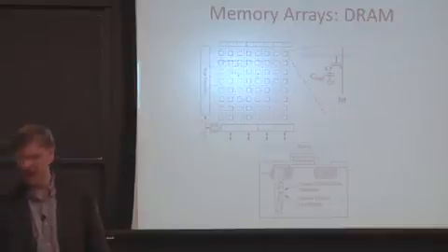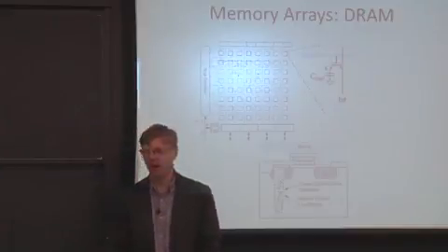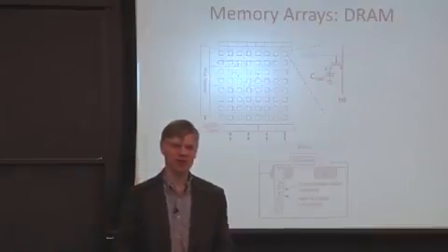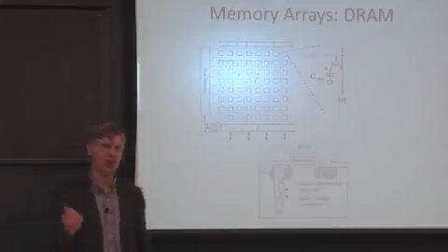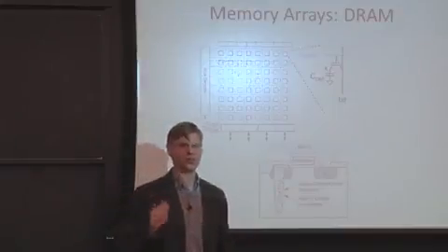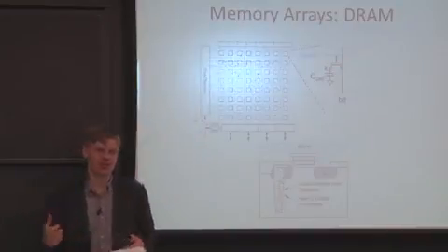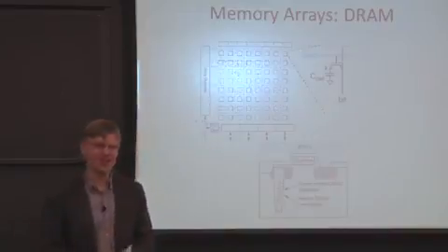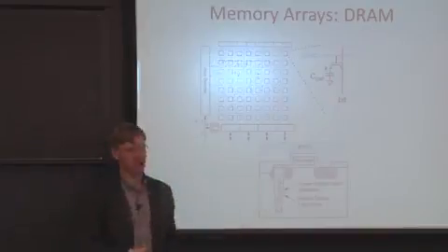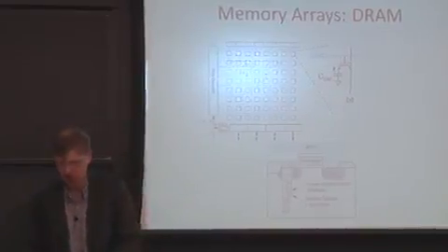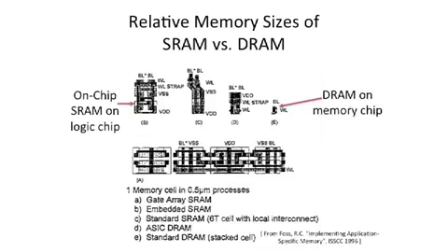Most RAM is actually decent now, and you've probably seen some attacks that people have built around this. Like there are some encryption attacks where people will effectively turn off a computer, pull the RAM out, and stick it in a different computer. The DRAM will still hold the charge, still hold the information, even after you remove the power from it, because this is a bunch of little capacitors that will store that charge. That's a funny little case where DRAM ends up being a negative. But we're really doing this to have more space to store data, because each of these bit cells is a lot smaller.